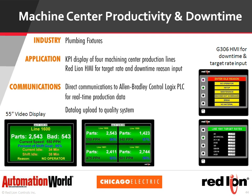Again, in this example, we were interfaced to an Allen Bradley ControlLogix PLC to pull real-time data, and added a couple more small touchscreens in order to be able to record downtime reasons. So that was a key issue for them, is they wanted to be able to start data logging downtime, and so we're doing that through the Redline HMI. We also used an HMI to load target rates, so that this system can be completely autonomous from any of the other software in the plant. You load the target rates in, and away you go.